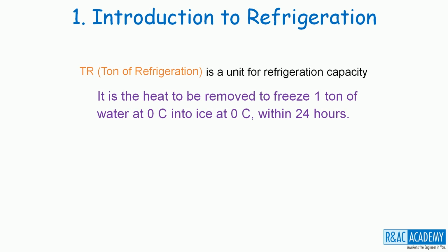What do we need to do for that? We need to remove heat from this water. But by how much? Equal to the latent heat of fusion for 1 ton of water. And we need to remove this much heat energy from water in 24 hours' time. This is how the ton of refrigeration was defined.